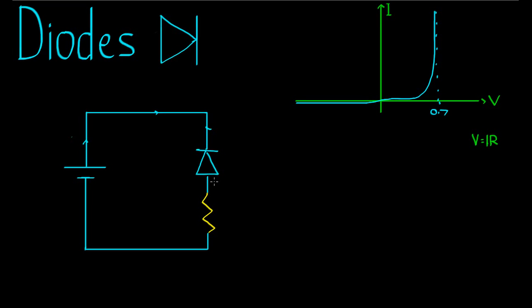And the behavior of the diode changes depending on the bias it's put in. When the diode is in forward bias, like this, that's another way of saying there is a positive voltage across it. So the voltage here is higher than here. The potential difference across here is higher than here. So we look at this section of the graph to see what behavior the diode obeys. And we can see that no matter how much voltage we try to push across this diode with the battery here, the diode never wants to accept more than 0.7 volts, say if it's a silicon diode.